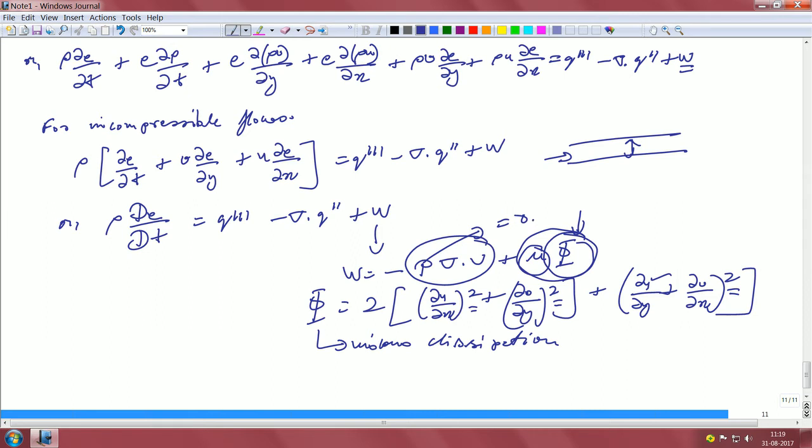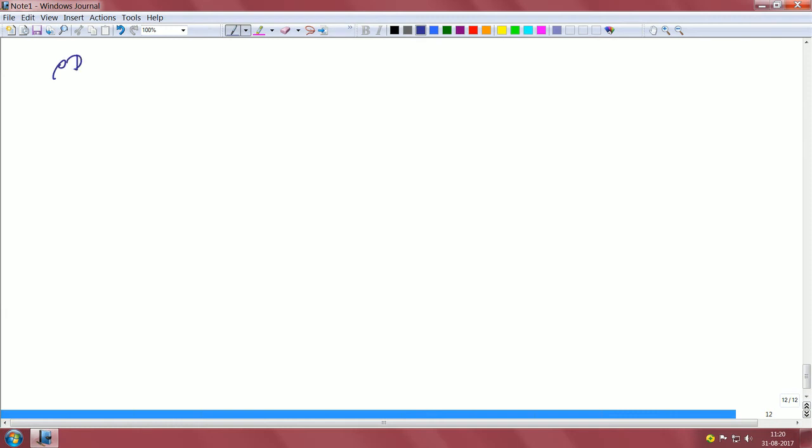If your viscosity is high, it can have effectively the same effect. That means if you try to push a very viscous fluid through a very narrow opening, you can generate a lot of heat. This is what sometimes happens in lubrication, where bearings and other things can get hot also. So, that is the expression for that. Let us look at the next one. Now, we have this combined expression.